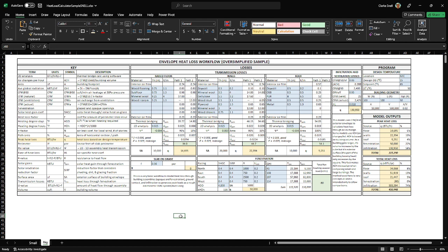Again, simple. There's this thing called the F value, which is heat loss factor. It's just a coefficient. There are 3 of them that usually are listed in books. I think this is the lowest. When a building's sitting on the ground, it's losing heat through the ground, but that's a different environment, so there's a different way to calculate it. Again, this is really kind of an old school way of doing it. You take the perimeter of the entire building, you apply this heat loss factor, and you get a Q value.